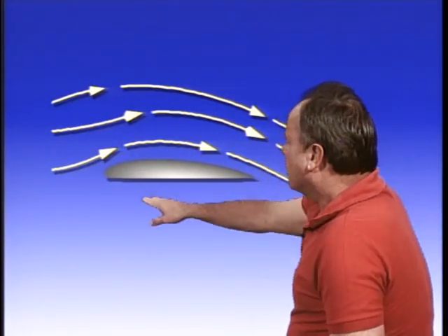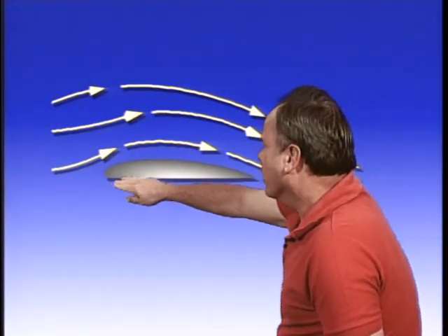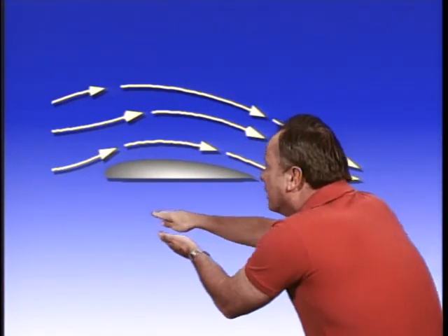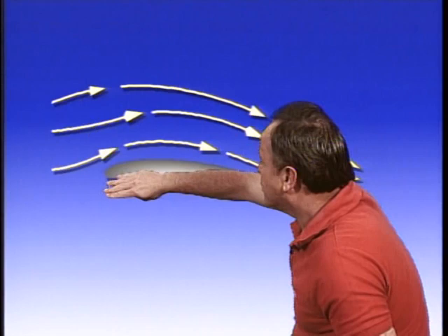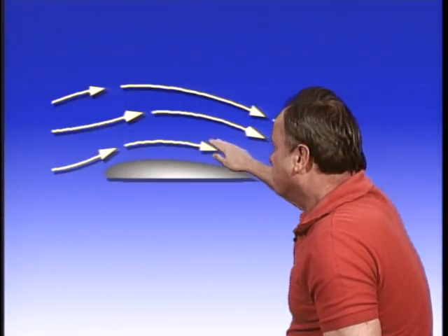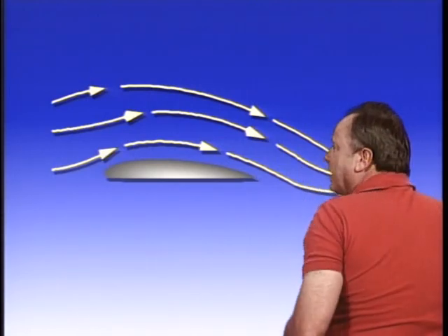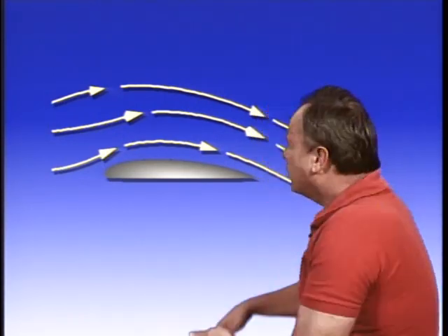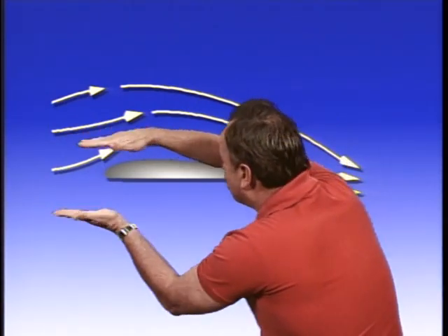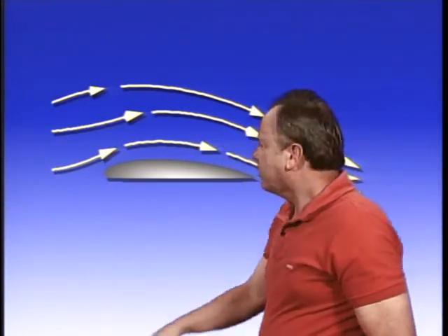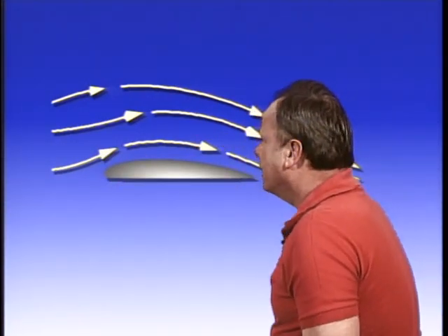So that's the principle upon which an airplane wing works. It's designed to produce lift, and it results from a relative positive pressure underneath the wing surface and negative pressure above the wing surface, and that's what creates lift. Now, if you increase the speed of the air going over this wing or the airfoil passing through the air, either way, you're going to increase lift because you'll have an increased differential. We always said the faster the fluid is going, the more differential there is.